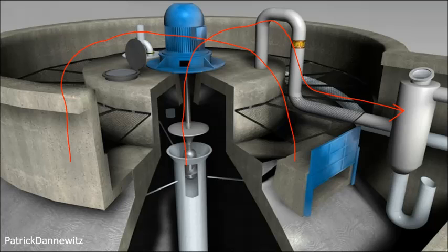So one question we might have is why an anaerobic sludge digester, if I said aerobic metabolism is faster. And there's a couple reasons. One is that it wouldn't produce the methane, or at least wouldn't produce as much of the methane or other potentially useful gases that we get out of anaerobic digestion. Also, it's just more expensive because then you have to have an enclosed tank, you have to be continuously pumping oxygen into it, and anaerobic metabolism is typically going to leave you with less residual undigested biomass or solid waste, which is important because the plant has to dispose of that.